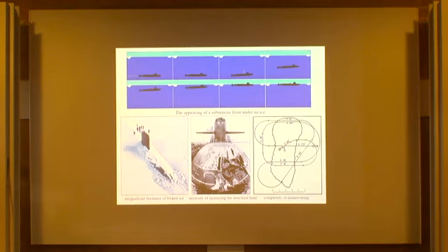These drawbacks can be eliminated by subjecting the ice cover to hydrodynamic loads with arrays near the bottom surface of a moving submarine vessel. With the help of flexural gravity waves in the ice cover caused by submarine vessels, destruction of the complete ice cover can be achieved, which will allow submarine vessels to emerge in thicker ice compared with the traditional method of surfacing.